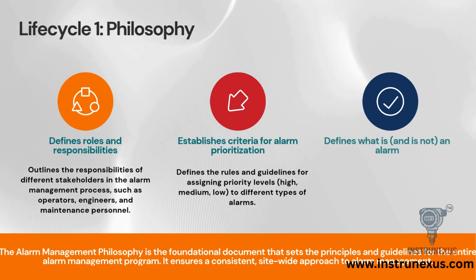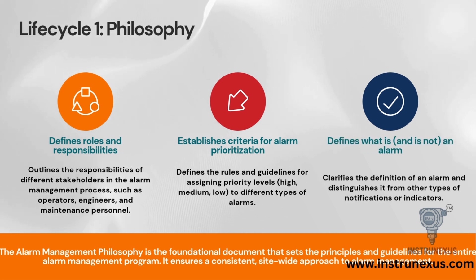Most importantly, it defines what is and what is not an alarm. If a notification doesn't require operator action, the philosophy document clarifies that it shouldn't be an alarm. This document sets the guidelines for the entire program and ensures consistency across your site.